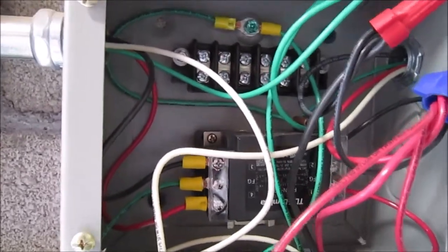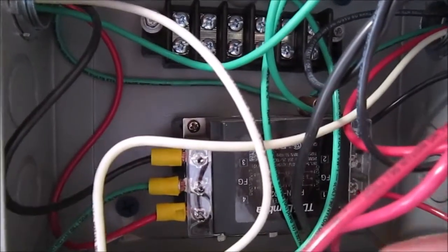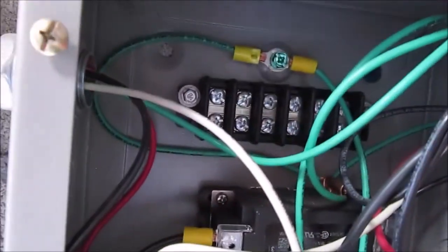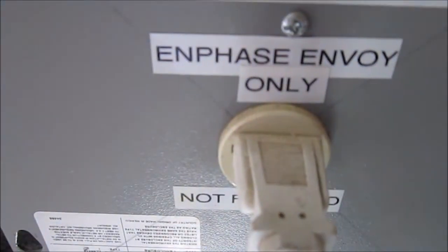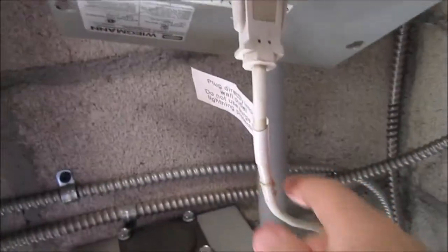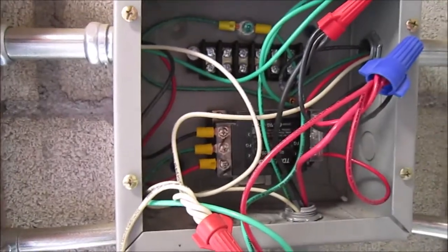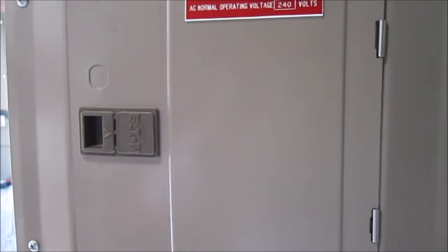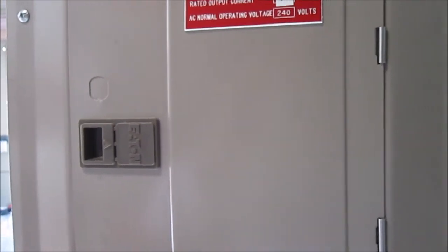The way it works is that the red leg on the N-phase side is tied into the receptacle, so the power line modulation signal can go right up to the N-phase envoy, but it's blocked from passing through into the sub panel so it doesn't interfere with the Insteon signals that control the rest of the house.